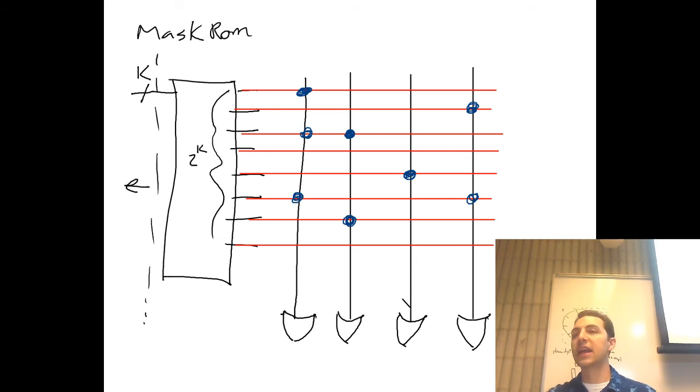So I have just connected these. Now, when I put a particular address in, let's, for the sake of argument, say I put in an address of 3. That would be a 0, 1, 1, 3 to 8 decoder. Which one of these lines will be activated? Well, it would be the 3rd line. So this is line 0, 1, 2, 3.